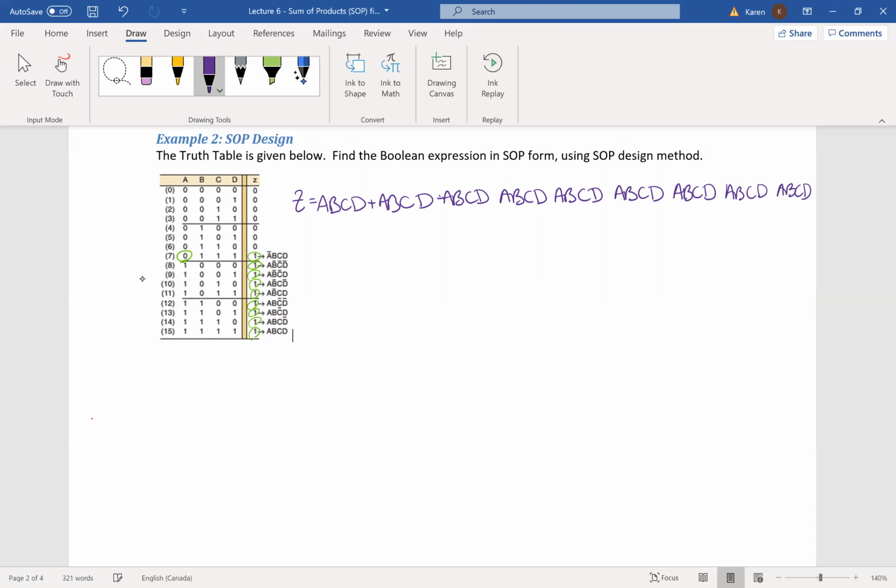And it's the sum of them all, or it's actually the OR gate of all of these ANDed factors. Now I have to transcribe the inversions. And I hope to not make an error in transcribing, but we all make mistakes. The last one has nothing inverted.